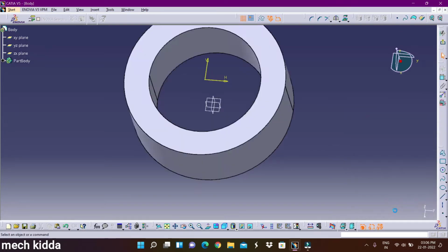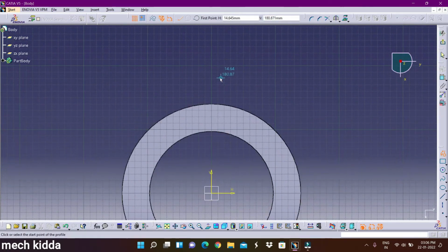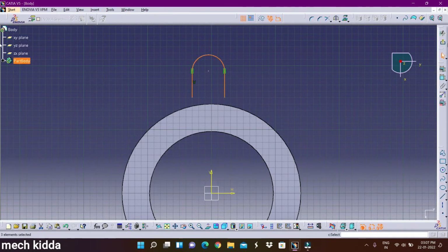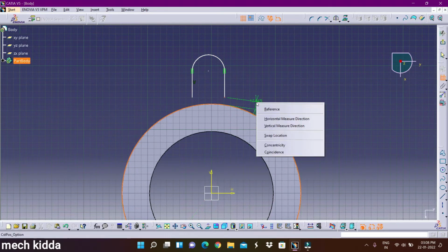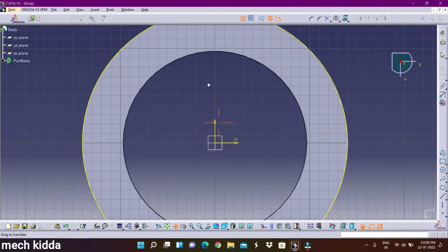Again we have to click to the sketch positioning for further sketch as our design requires. Here we have to use profile tool for complex design. After doing the design, we have to select project 3D element to generate the surface in the circular region. Now we have to select the constraint to make the surface and the 2D sketch coincide and dimension the 2D sketch as well.